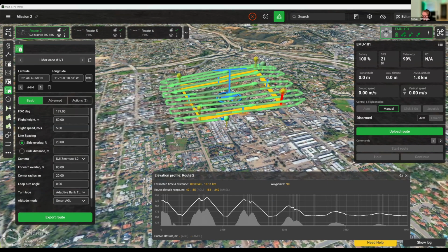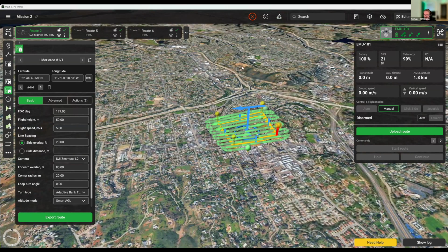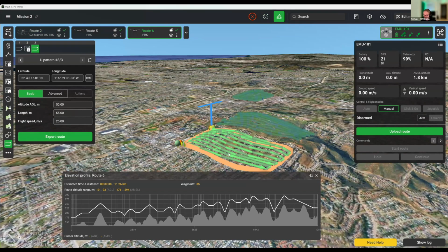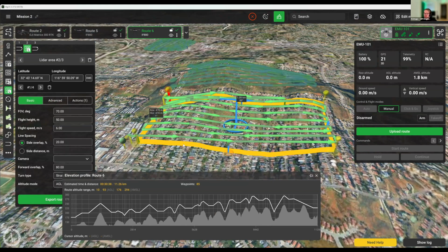Okay, next question. When flying from flat to steep terrain, is there a recommendation or possibility for reducing speed? Also a great question. And this is actually done automatically by UGCS. I'll maybe try to now explain a bit how it exactly works. Let's say we have this route. We can also see the elevation profile that's here, which is actually, even though it's suburbs, quite mountainous suburbs. So in here, what UGCS does is that it always checks what's the maximum descent and ascent speed.